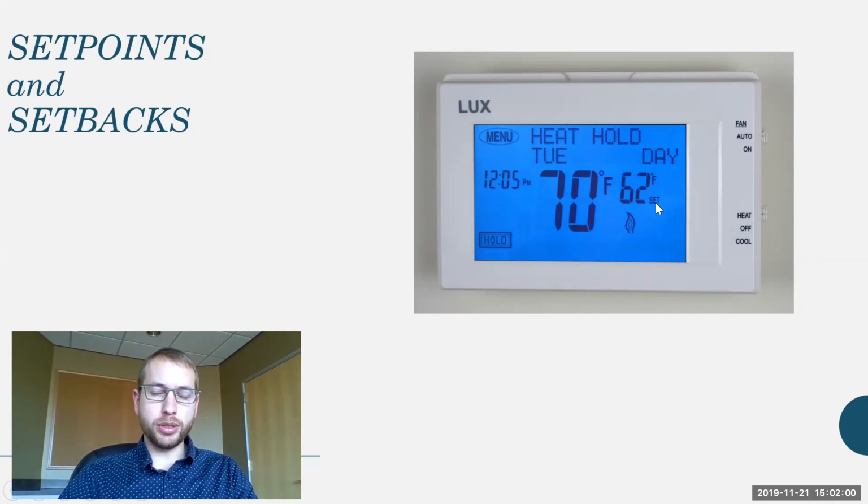We shouldn't waste cooling energy if nobody's going to be in the space and there aren't any loads or say pieces of equipment that need to be kept at a certain temperature. So make sure that the set point is reasonable. It might have a range, say between 70 to 75 degrees, where no heating or cooling is required, and that the setback temperature is enabled.